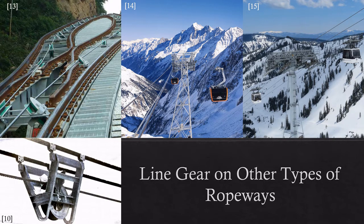As you can imagine, line gear is highly specific to the type of ropeway you're working with. Some examples are given here. On the top left, there are the tracks and deviation shifts for a funicular. The top middle shows a tower on a 3S gondola. The top right shows a tower on a funitel system. And the bottom left shows a slat carrier, which is used on an aerial tramway or tri-cable ropeway.